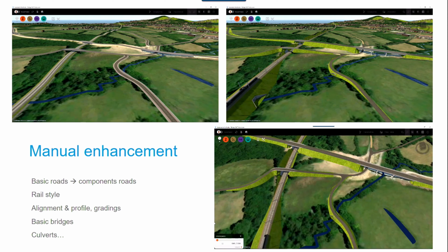And in this phase, I've created the first proposition for the bridge. It's not shown here in the video, but it's the very basic first manipulation when you want to work on a bridge. You just select a road and use the technical module of InfraWorks for bridges, and you just ask for the start station and the end station of the bridge, and InfraWorks proposes a default model of a bridge. In 3 clicks with your mouse, you have a bridge.